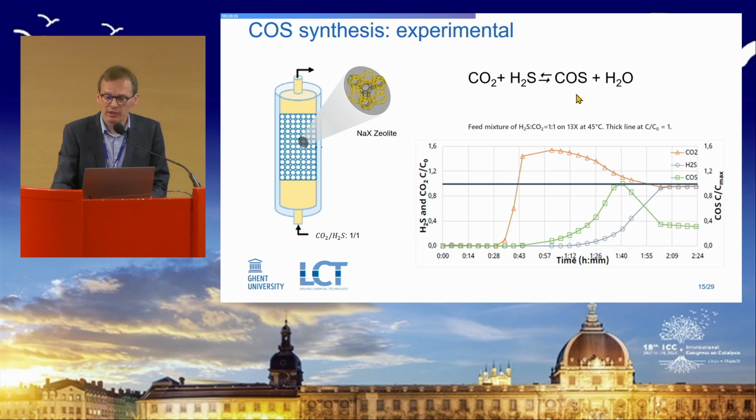From the moment there is also H2S and some carbonyl sulfide is being formed, carbon dioxide is being pushed out of the catalyst bed, and that is why we see this roll-up occurring over here. The second component to appear is the carbonyl sulfide, which is being formed.